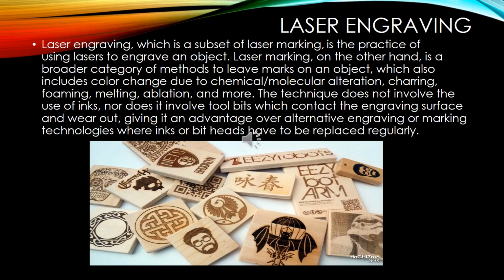But when a laser hits glass or stone, sometimes something else interesting happens. It fractures. Pores in the surface expose natural grains and crystalline spots which, when heated very quickly, can separate a microscopic-sized chip from the surface because the hot piece is expanding relative to its surroundings. So lasers are indeed used to engrave on glass, and if the power, speed and focus are used right, excellent